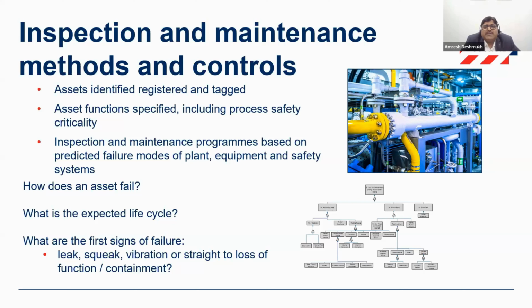What one needs to do is, based on the criticality, there has to be a criteria which clearly says that for critical equipments, there is no leeway. There's no program on site which will give me some leeway to avoid that maintenance and move on with my regular manufacturing practice. I have to do the maintenance for critical assets on time. There's no exception to that.